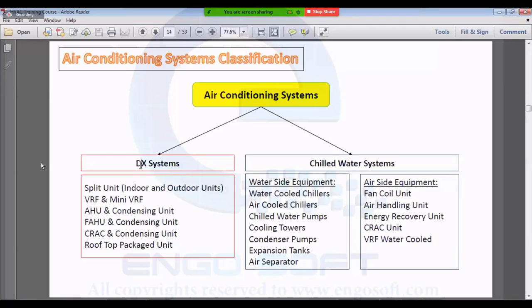So in the other case, to save money, the space wants only 30 liters per second of fresh air. It doesn't want 100 liters per second of fresh air. So I take 30 liters per second at 46 degrees from the outside, and mix it with 70 liters per second from the space, which is at 24.